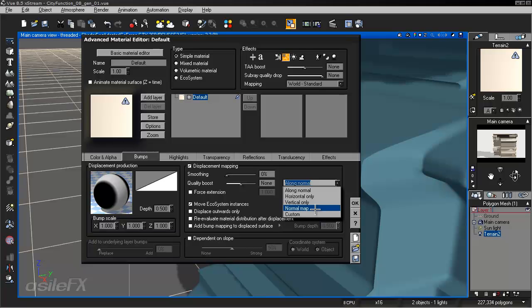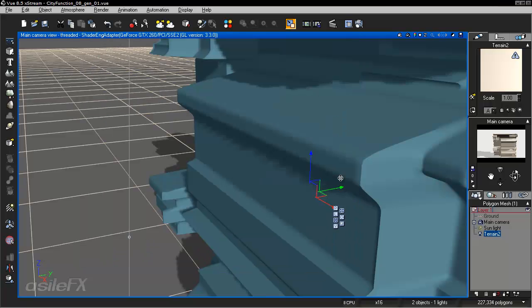A normal map basically tells the object where the normal is facing, rather than it just being in the position it is. It will manipulate it so that you can create some pretty interesting effects that way. You can also set up a custom displacement in order to manipulate the XYZ vector manually, which is what I like to do for horizontal and vertical, because you can just hit 0 on the node that is created for that axis, and it works a little better sometimes. Really depends. So let's go ahead and right-click, Bake to Polygons,